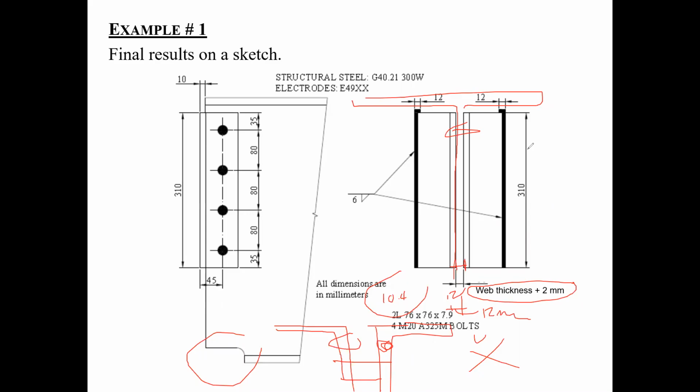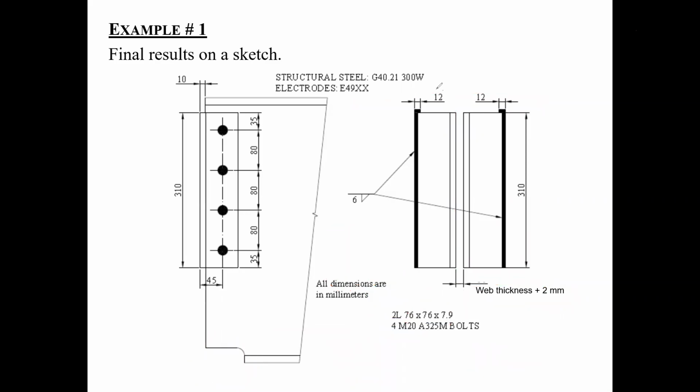If you want to be more generous, you can go up to 1/8 of an inch, 3 millimeters, you understand? But 2 millimeters minimum that you should be specifying here, maximum 3 millimeters, okay, 1/8 of an inch, and that's the maximum gap. And on top of that, the return should only be 2D. So therefore, the return here is 12 millimeters.